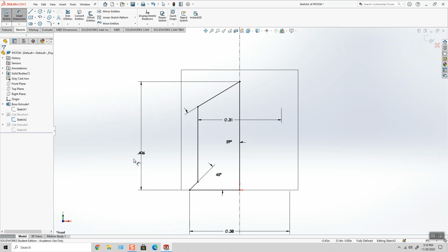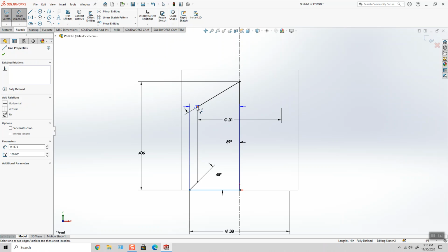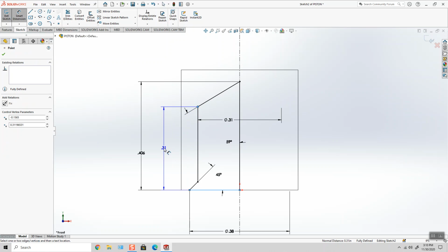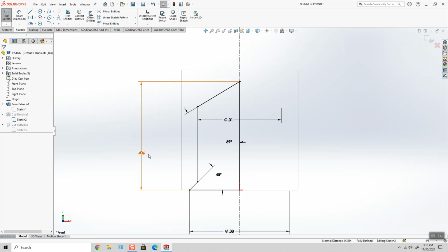A traditional hole depth is always dimensioned to the end of the body diameter like this. So the depth of this hole is technically 0.31. The way that this author dimensioned this hole is bogus. So please don't ever do it like this. This is what they were trying to accomplish by making sure that the drill point didn't pierce through the piston. So this should have been dimensioned explicitly on the print, and it wasn't. So that's a mistake on their end.